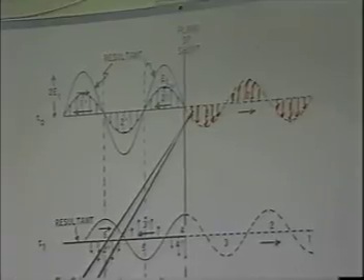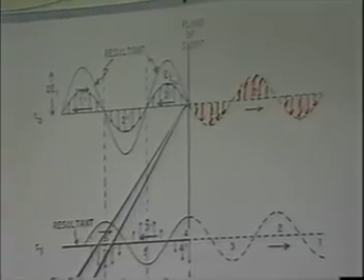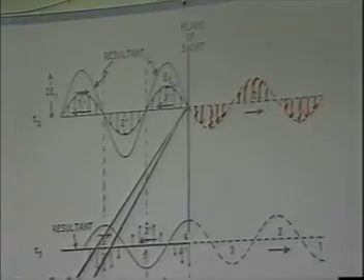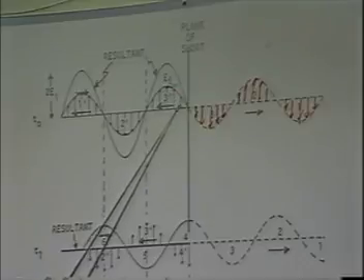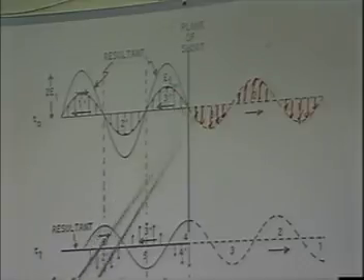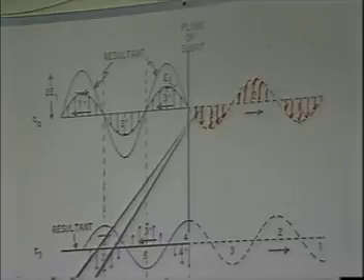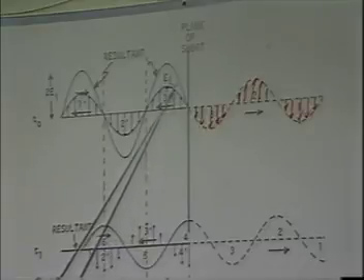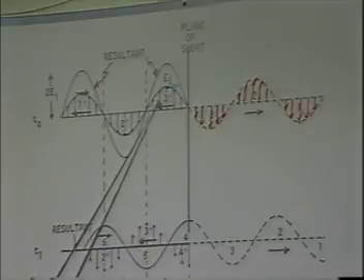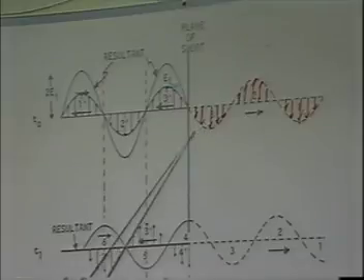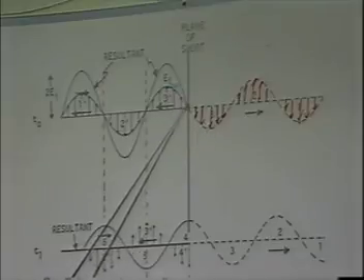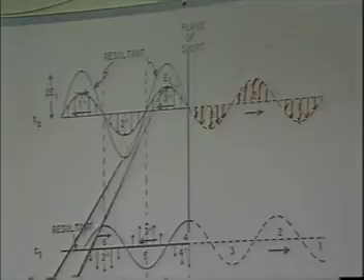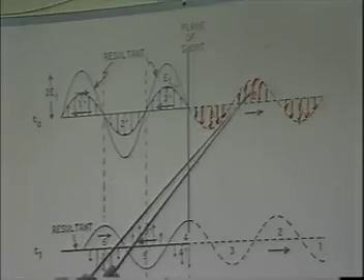Let's take this one right here. Instead of going to the right 30 degrees, it hit this surface here, which is a short circuit, was reflected out of phase, and went back here 30 degrees this direction. The next one, instead of being negative here, it is positive over here, going in this direction at the speed of light. This one, instead of traveling 90 degrees over here, it travels 90 degrees this way, and it is positive instead of negative.